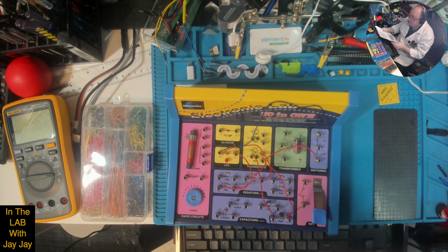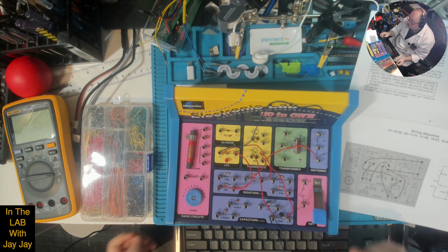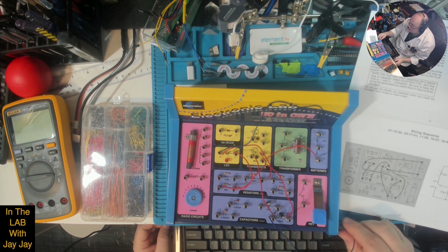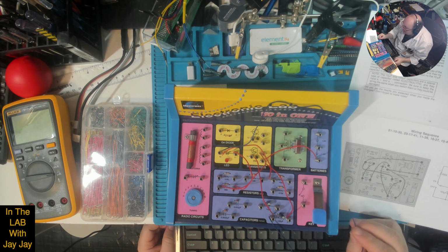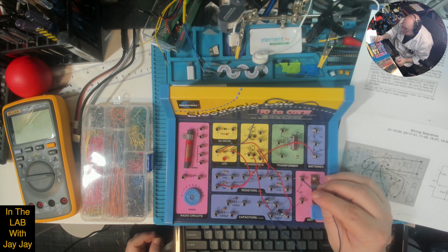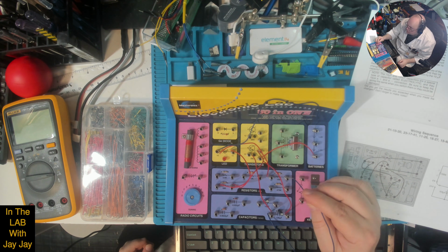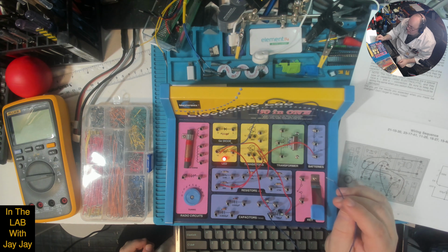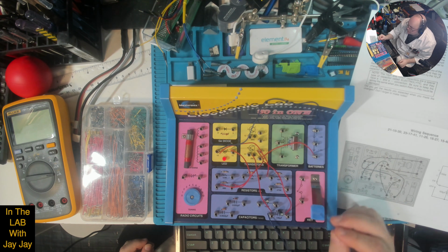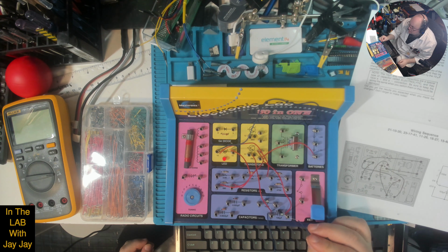Now the instructions say to take a wire, this is the wire, and attach it to pin 31, which is on this side of the 100 kilo ohm resistor. So when we do that, we hold it there, nothing, nothing, nothing, and bang, the LED lights up. Then we take it away and the LED slowly goes down, down, down. If we want to speed it up, we can discharge the capacitor just by shorting its terminals, which we do now, and that goes all the way back down to 0.